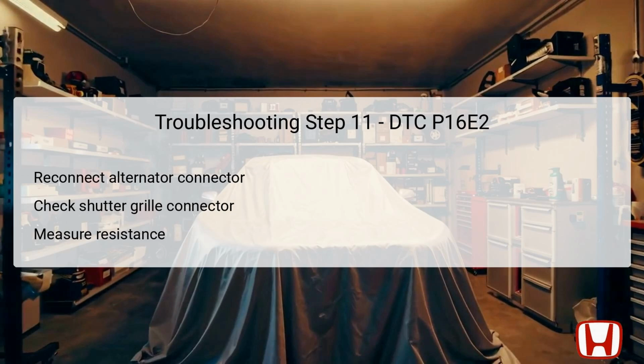Resistance of 1 megaohm or higher leads toward the next troubleshooting actions, while results indicating otherwise will point primarily toward an issue with the alternator in need of replacement.